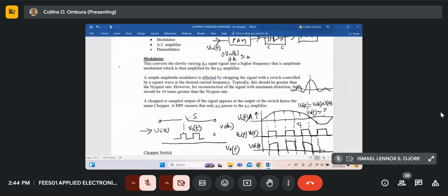As the width of the rectangular waveform becomes very thin, the sinc function expands, and at the limit it becomes just flat. You get all the spectra. So that is how frequency translation is effected. I'll demonstrate that with a simple example after this.